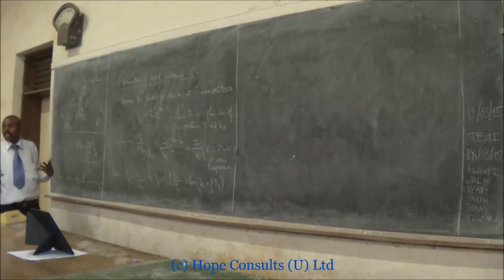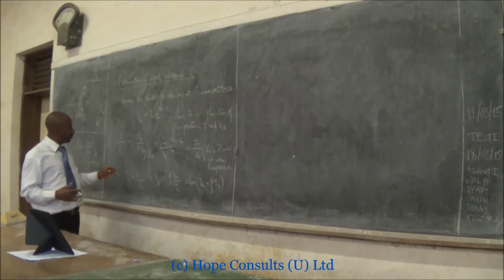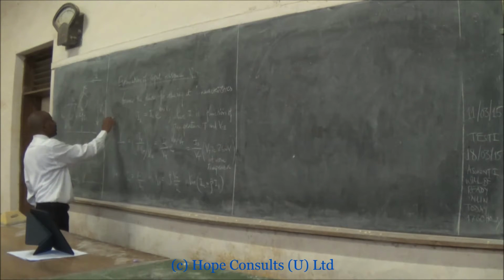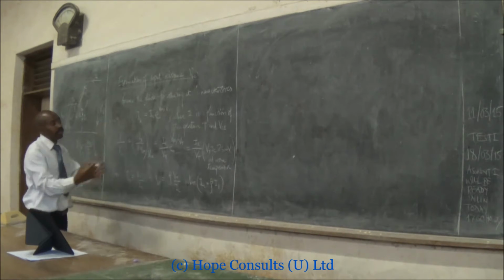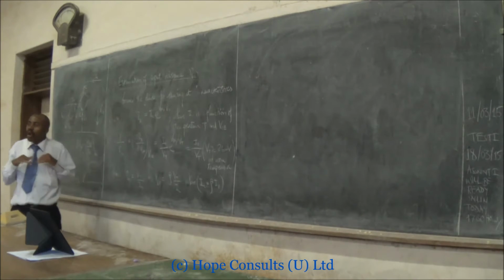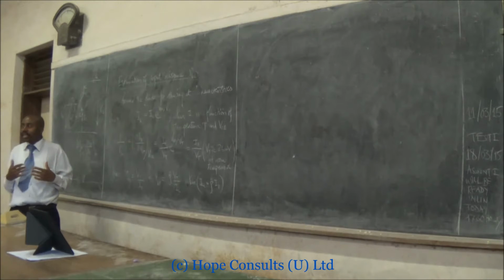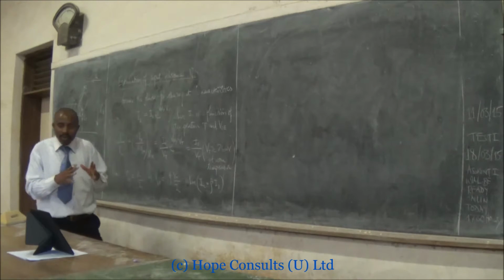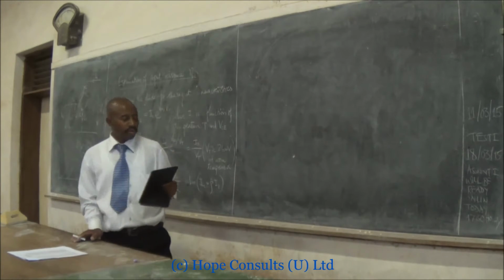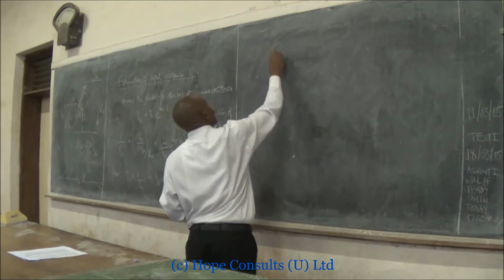We need to represent it in terms of these other resistances. This would be the input resistance. We have another one, RCE, for the output impedance. Then we can know how the current is flowing in and out. For that matter, we talk of the small signal equivalent circuit.